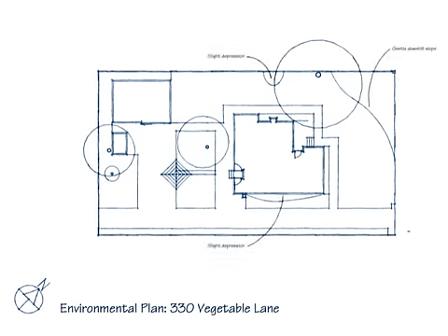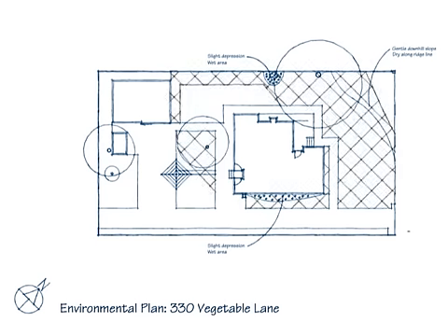Next, we will add the location of the dry and wet spots on this site, as these often relate to site contours. Then we will add the location of those parts of the section that don't get at least 6 hours of sun each day. In this example, we will use loose cross-hatching. We got this information from our sun study. Finally, we will note the direction that the wind comes from most of the time. This is called the prevailing wind.